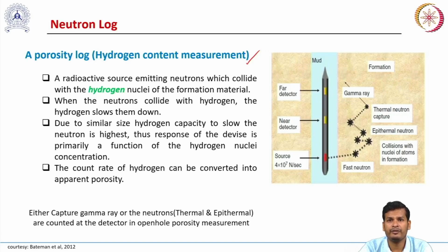So whether we should use the bulk density data or the bulk density of the formation to calculate the porosity may be controlled by our delta rho correction values. That's why it is always important to remember what my tool's primary measurement is. My tool's primary measurement is not the porosity. My tool's primary measurement is the hydrogen content. So whether this hydrogen content is reliable or not should be established first, before calculating or inferring the porosity values from our hydrogen index measurement.